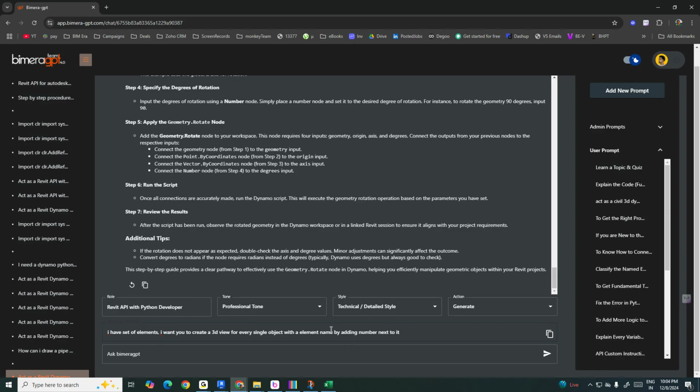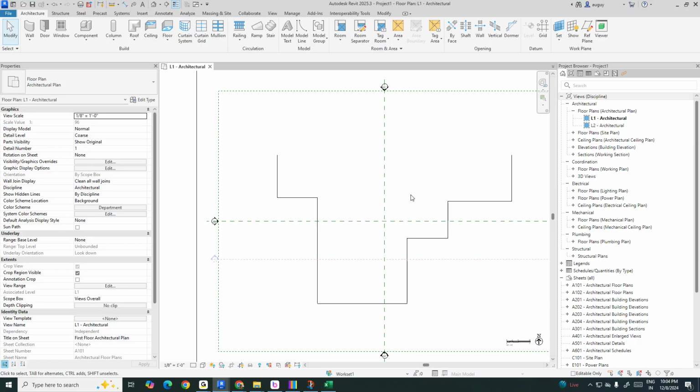So if I have 10 elements selected, element 1 gets a view, element 2 another view, element 3 another view, all 3D views. Is this clear? If you have any clashes, we generally do that. Creating clash views, exactly like Navisworks, is possible.